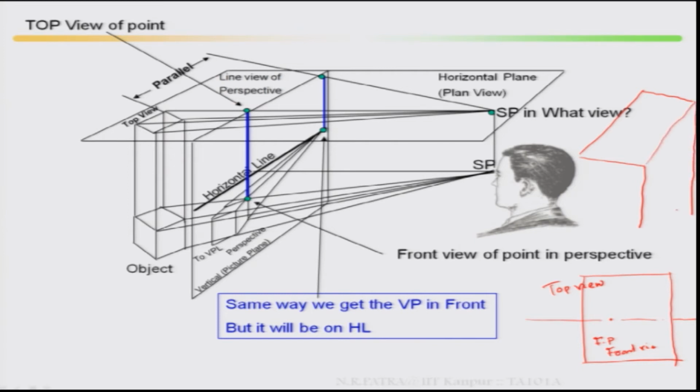Take a piece of paper and move it, so this is your horizontal plane HP, this is your frontal plane. Here will be your front view, from here will be your top view, and this will be your hinge line. Along this hinge line, if I rotate, it becomes like a two dimensional case.